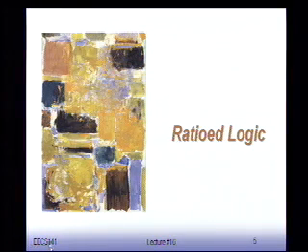If we look at complex logic gates, we see that its logical effort is not that good. Compared to an inverter, a 2-input NAND already has 4/3 logical effort, and it goes up quite rapidly if I increase the fan-in. And why is that?